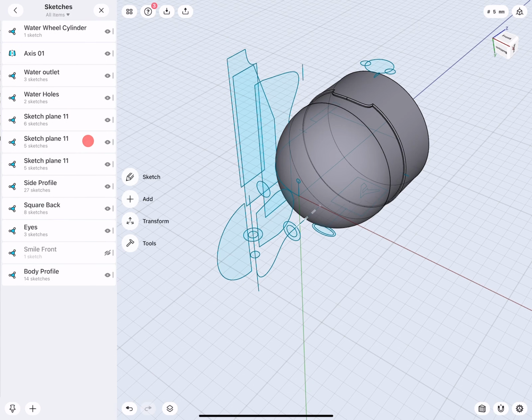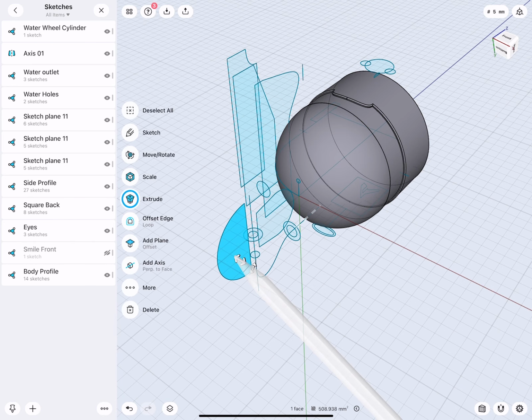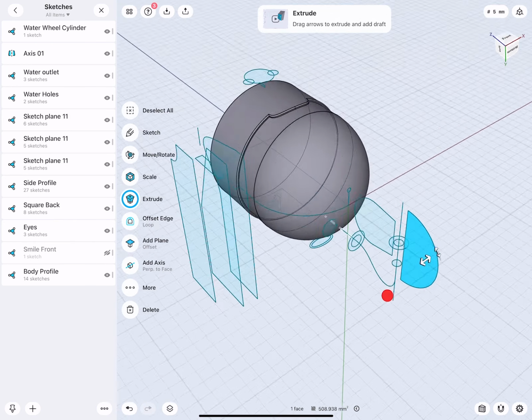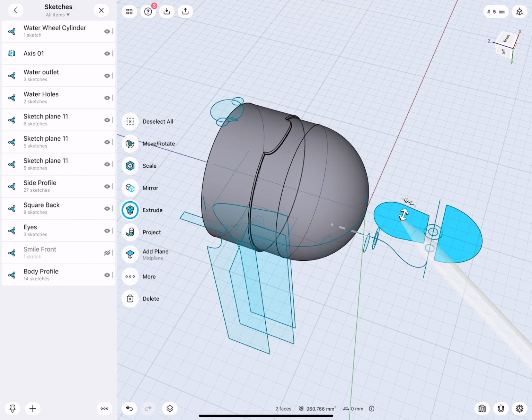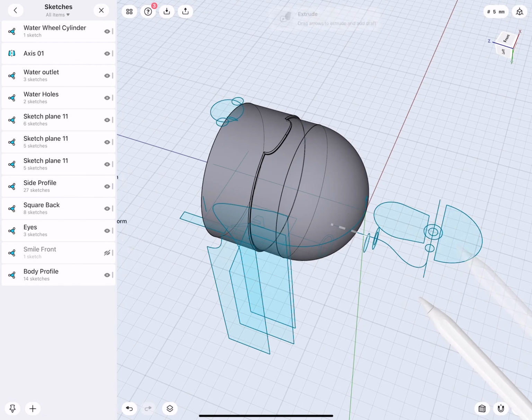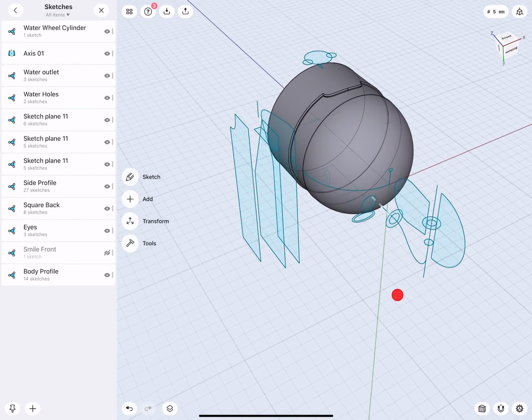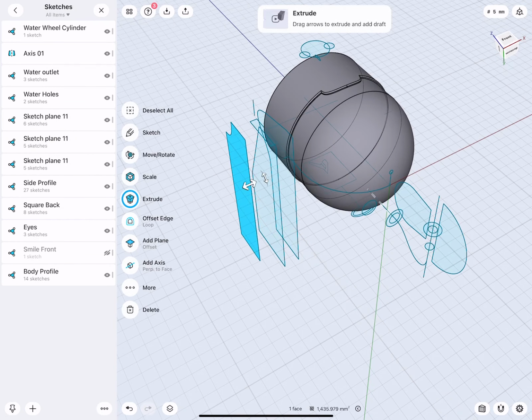When we move those in and out, you have to be careful that this actually will change the name of a sketch. Because here, let's select the sketch and this. They're all basically on the same plane, more or less, if you want to see it this way. And they have one name. So when a sketch is moved onto the same plane, they're fused together.